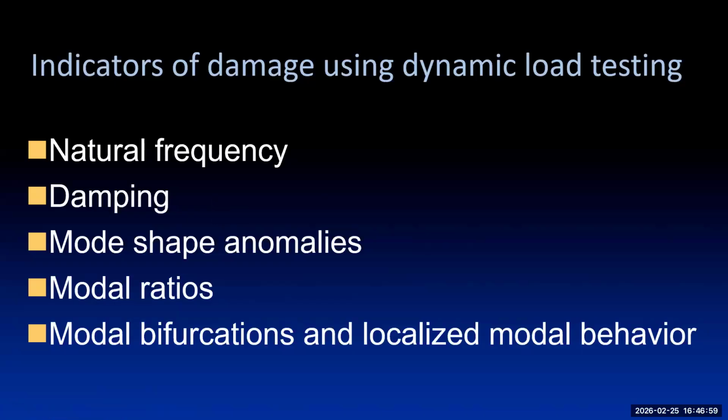So if you're going to find that displacement per unit force characteristic, you need to know the natural frequency and damping in their nonlinear form. And being able to do that with damping is not straightforward at all. However, we've done it. We've done it on more than 100 structures, and we find that when we couple it together with fracture mechanics, the science of fracture mechanics, all of the problems that occur in the building actually jump out at you.